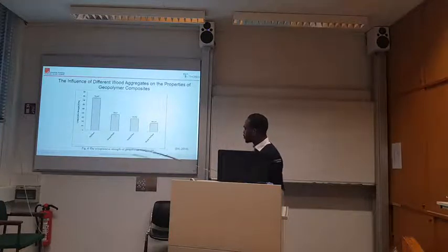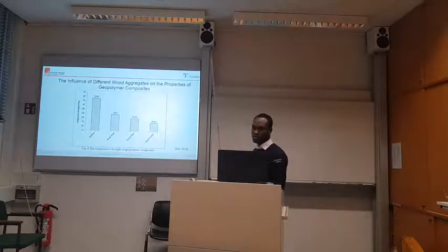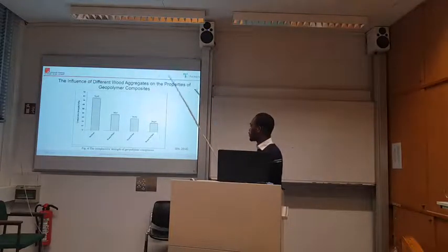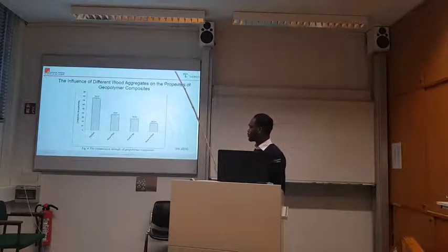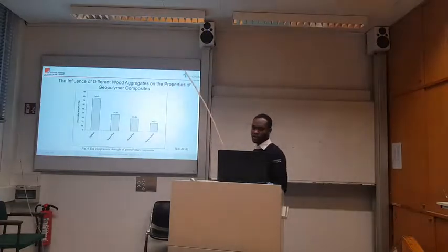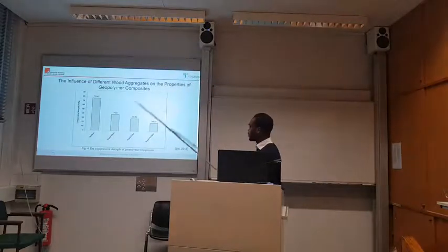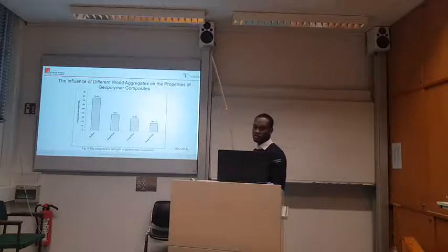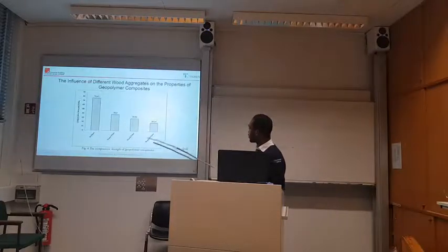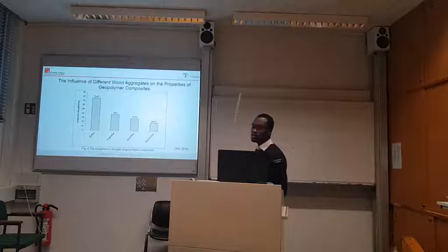And when we replace it with 20% of wood flour, so very fine wood, the strength is somewhere around 38. So cut to about half with 20%. Then when we put in wood fiber, the strength goes down. Then when we put in wood particles, the strength goes down.